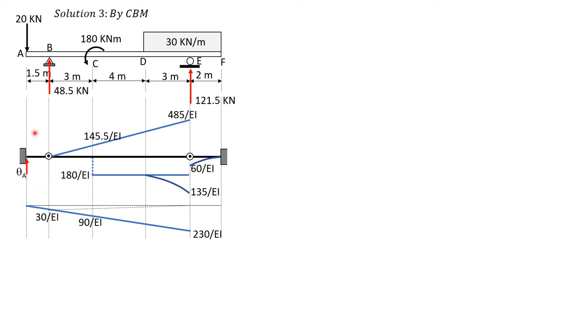So we have theta A upward, clockwise, delta A, assume positive deflections, and of course corresponding shear and moment respectively. Then at B, just to the left, downward, and upward for positive shear or theta at B. Then at E, down just to the left, up just to the right. So that's it.